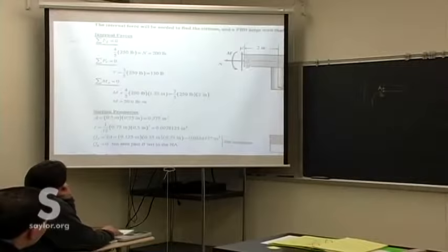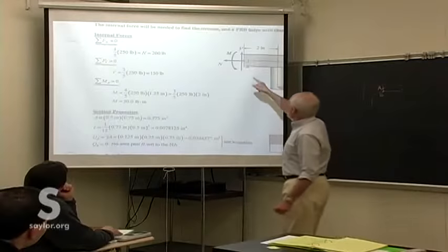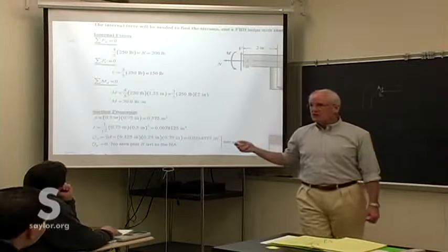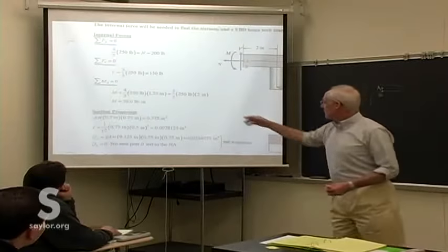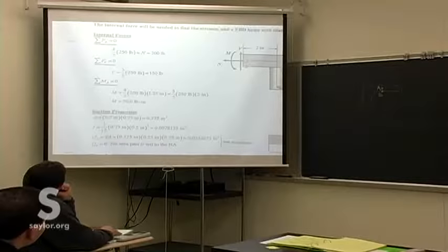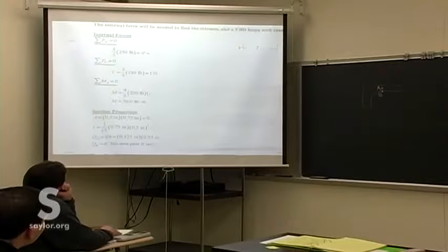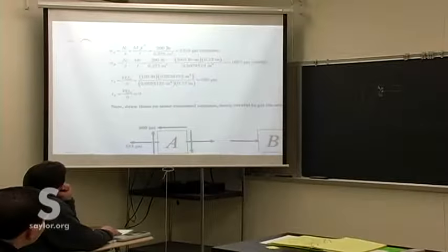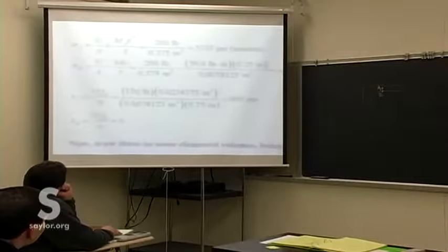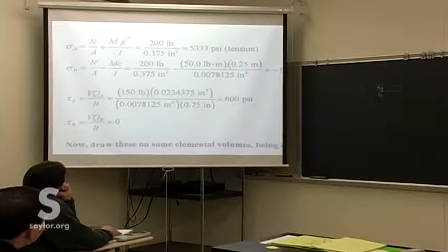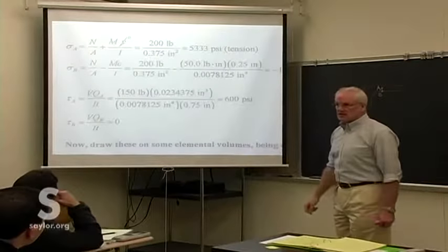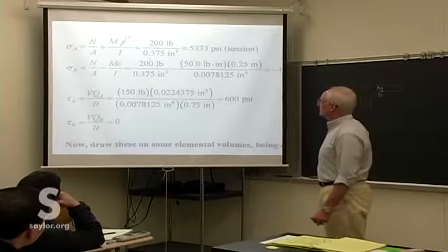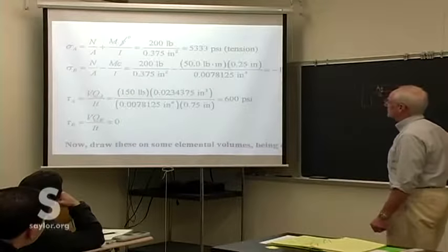First thing I had to do was figure out the internal forces at that face, because it's those forces that determine what the stresses are, combined with the section properties, which is just the pure geometry of the situation, and then the individual stresses were found for the different points.